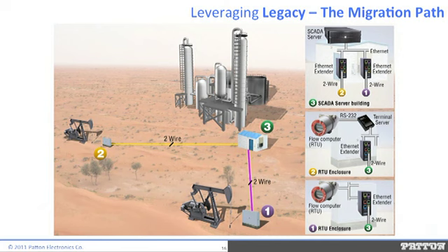Let's look at the modified gas and oil application scenario in the migration from legacy to Ethernet. The two incremental scenarios show the cost-effective and technically easy way of migration. It can be incremental step number one. Consider wanting to use your flow computer with an RS-232 interface that's already deployed. We want to connect it to the Ethernet port of the SCADA server.